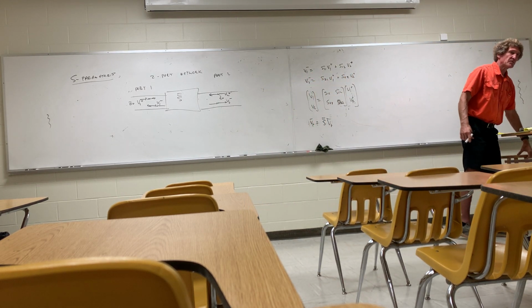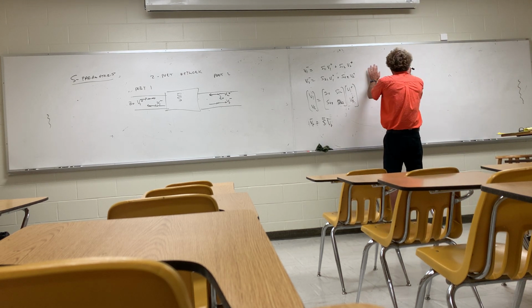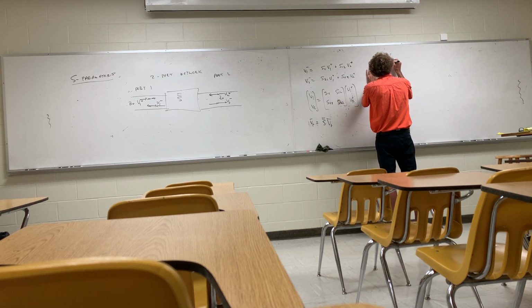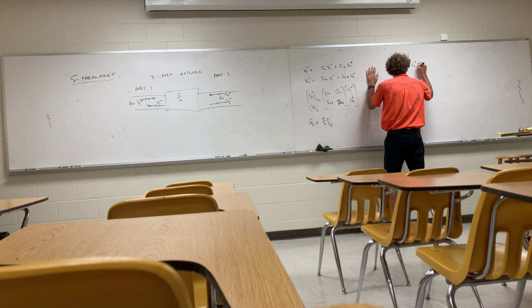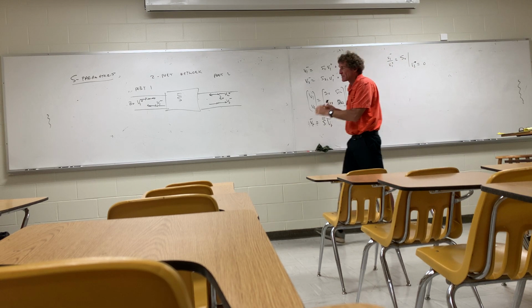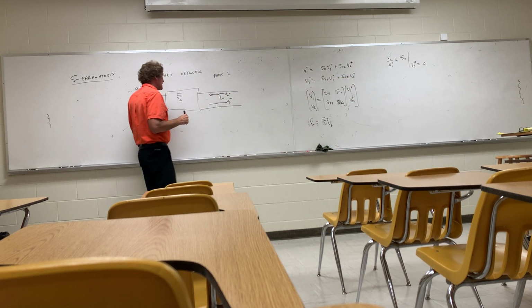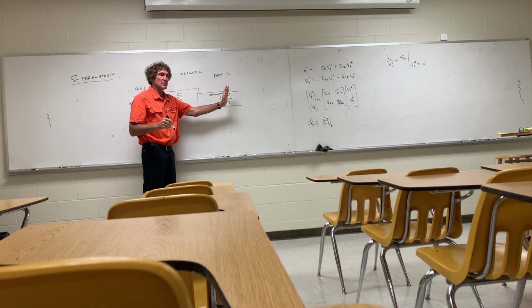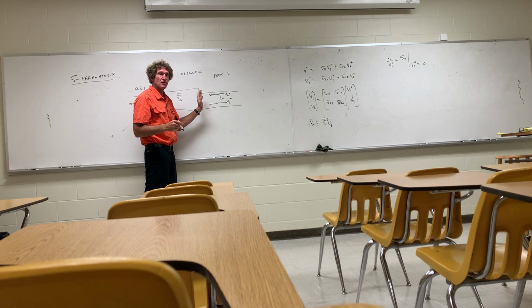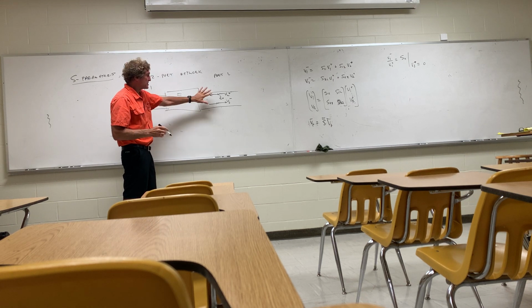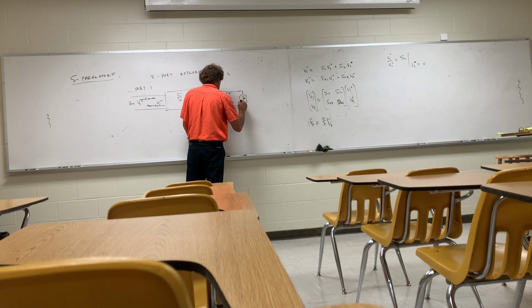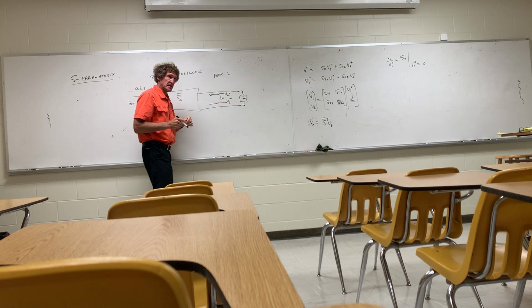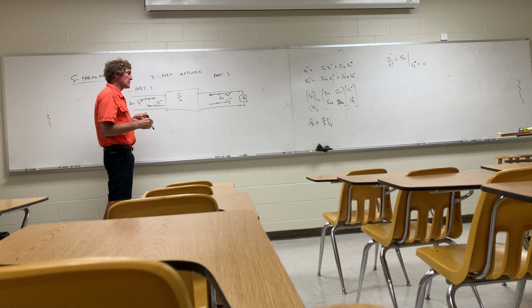This is voltage. So if you look at this, when I take a look at V1 minus over V1 plus, that will be S11, assuming V2 plus is equal to 0. Let me try to explain this. If you have no signal coming into port 2, V2 plus is zero, then effectively what you have is a matched condition over here. There'll be some load that would have Z naught effectively. And any wave that comes out of here is going to be just dissipated into that. There's no reflected wave, no V2 plus.